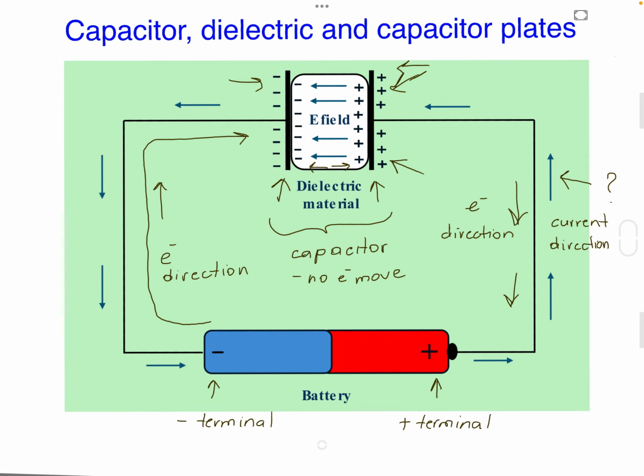What's this capacitor? I just mentioned that it stores the charge, due to rearrangement, etc. But let's go a little bit deeper with that. You have two metal plates separated by an insulating material, called dielectric material. I wrote it down there. When you connect the battery, electrons start flowing in the external circuit. They pile up on the negative plate and are pulled off the positive plate, just like I explained a few minutes ago. But inside the capacitor gap, the dielectric prevents electrons from actually crossing over.